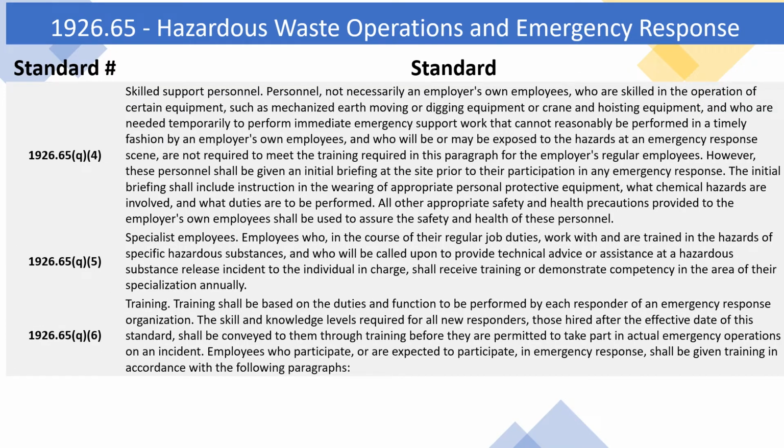1926.65 Q3 Procedures for handling emergency response. 1. The senior emergency response official responding to an emergency shall become the individual in charge of a site-specific incident command system (ICS). All emergency responders and their communication shall be coordinated and controlled through the individual in charge of the ICS, assisted by the senior official present for each employer.